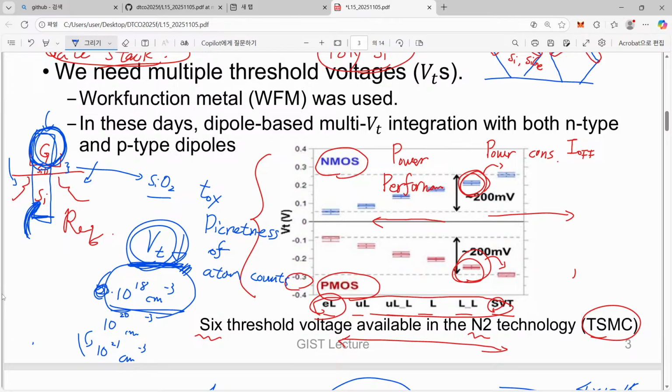Doping density nowadays is just kept at low values like 10 to the 16 or 10 to the 17. These numbers can be regarded as just nothing. Of course, compared with the intrinsic carrier density, 10 to the 10, 10 to the 16, 10 to the 17 is more than a million times or 10 million times higher. However, from the viewpoint of doping density, that number is not significant at all.